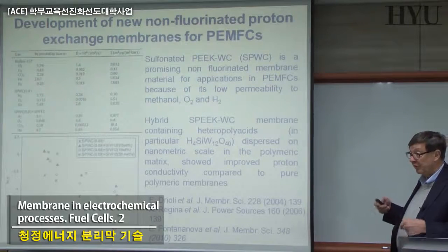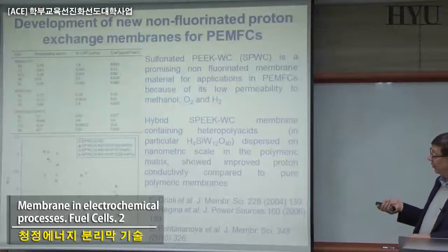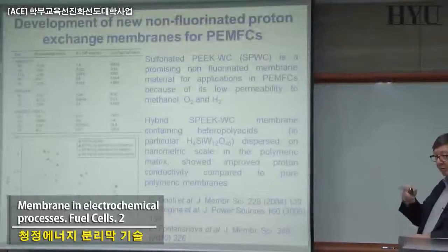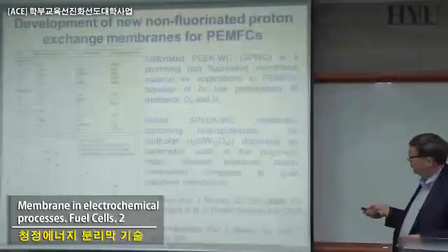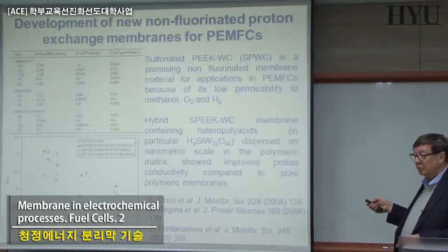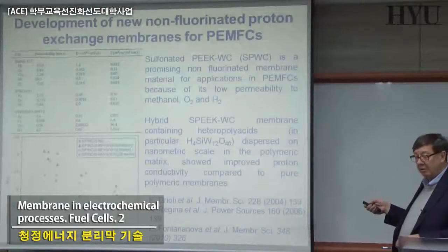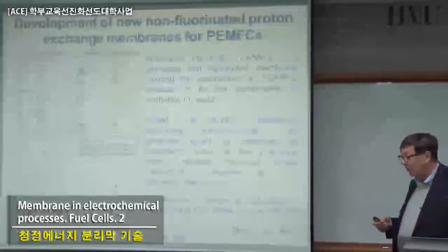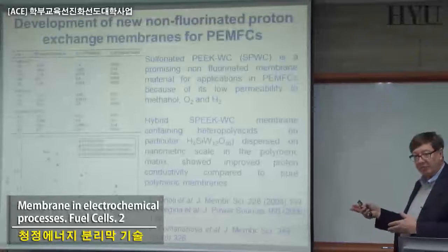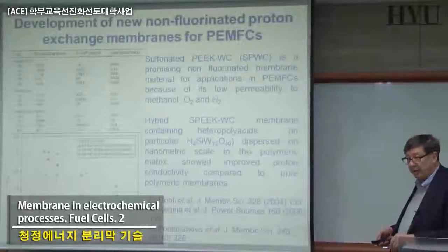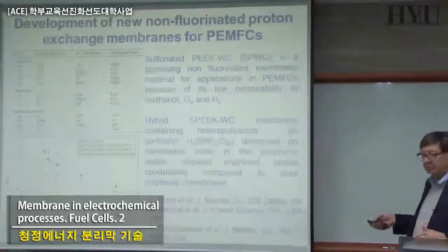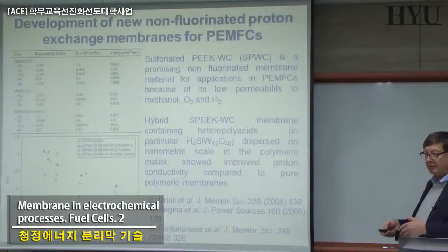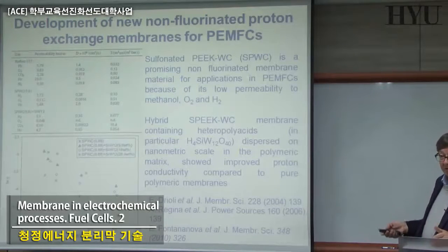A few years ago, one of our Chinese students, in fact, who has been working in Changchun, not too far from here in Manchuria, was able to introduce this cardo group in the structure of polyether ether ketone, making this kind of PEEK soluble. So now when you have a PEEK with cardo group, you can directly, without sulfonation, in principle, cast using phase inversion, producing your membranes. And in fact, we have been producing membranes for many applications, from gas separation to fuel cell and other kinds of things.